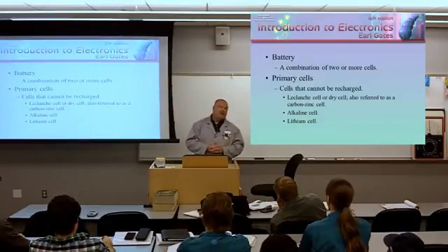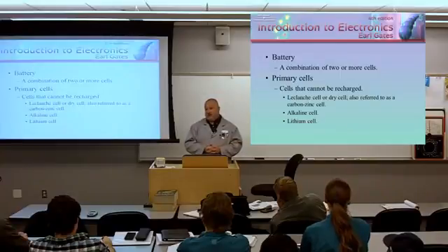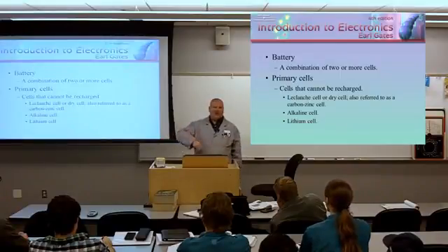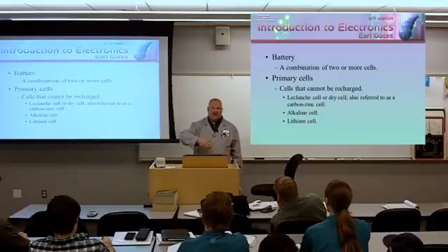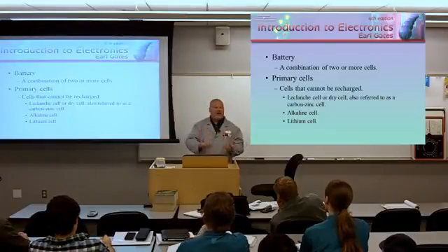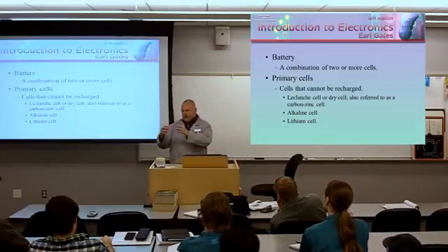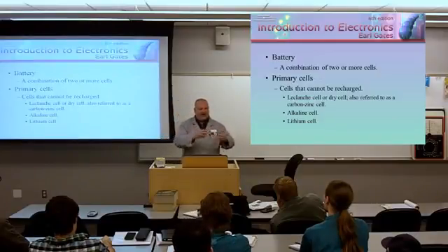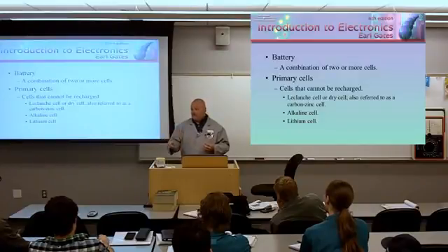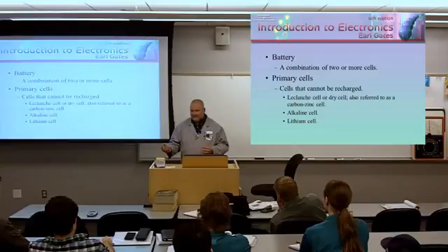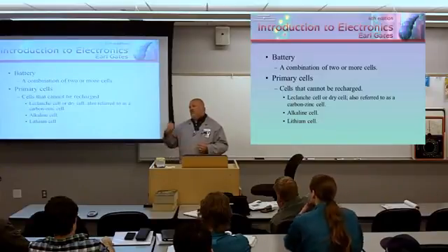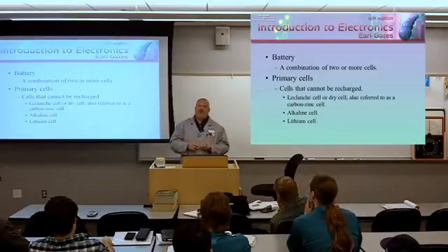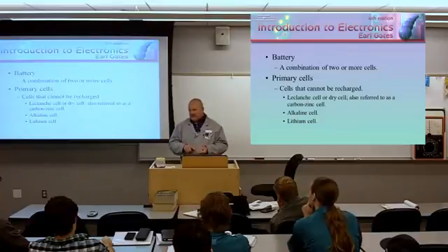I was really jazzed and excited when I saw these come on the market as a consumer-based product, because the lithium batteries before were unique. The manufacturer would put it together, and you'd have to buy the replacement from them, because the FAA requires that every 24 months you replace that cell whether you've used it or not. The sizes I'm aware of are AAA and AA.